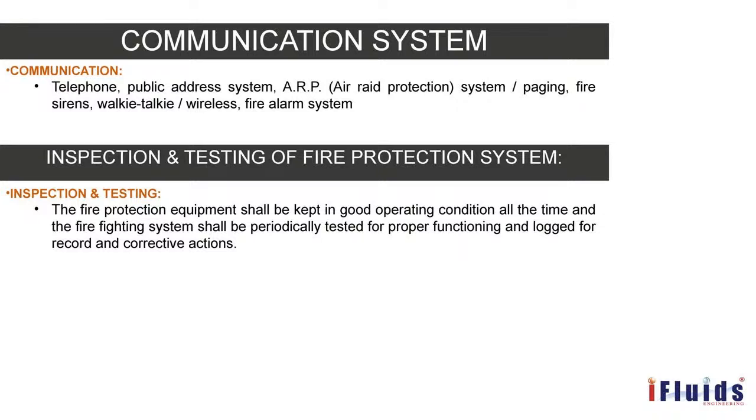And if there are floating leaves and materials, they have to be cleaned and removed once in 6 months, or whenever required according to your own facility condition. You need to clean any leaves or similar obstructions present, because they can interrupt the flow, so it has to be periodically inspected and cleaned.